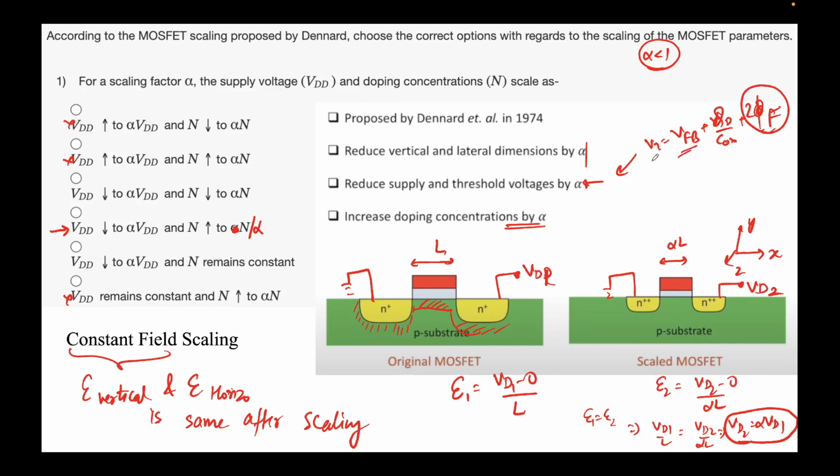So that also gets scaled. So everything has to be scaled. Every voltage has to be scaled, right? And these are the fundamental things. So if you recall the expression for ID, you have Cox W by L, and you have VT, right? Those terms are there, correct? It is a function of VT. So this gets scaled, ID gets scaled. For all other parameters, power is voltage times current. So all those things get scaled by some factors.